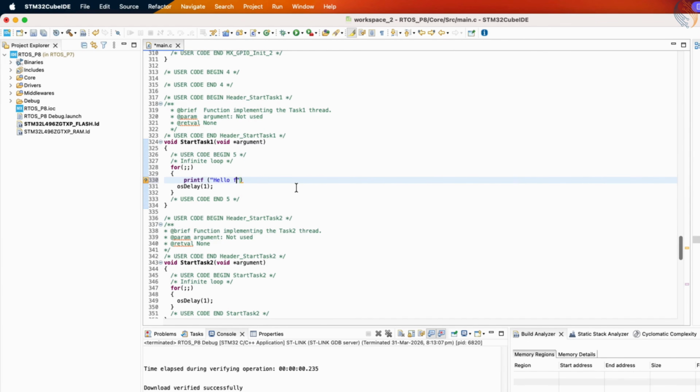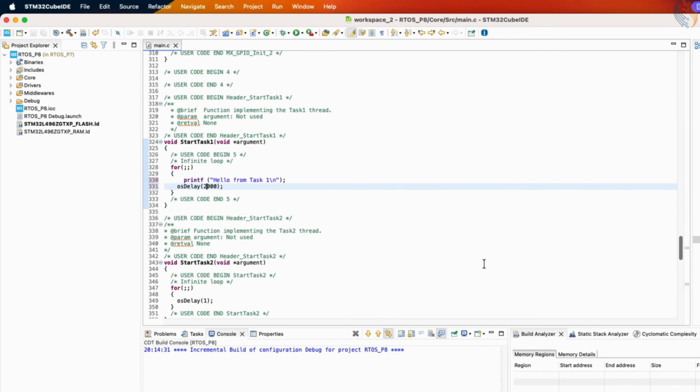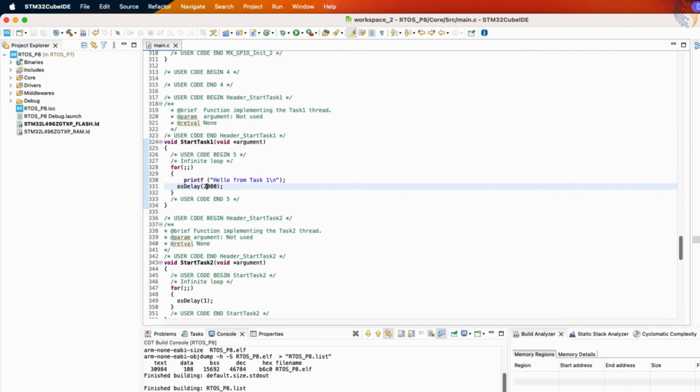That's why it is essential for you to monitor the stack usage according to your specific microcontroller, and the unique requirements of your project, and based on those measurements, you can make informed decisions about how much stack space each task needs, and how much code you can safely write inside it without causing problems.